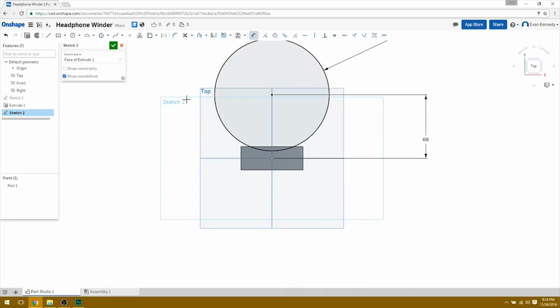So you could either get your circle tool out again and draw another circle and dimension it and position it. Or, just to introduce you to a new tool, we can mirror this. If you click on this mirror tool up here, it says select a mirror line. So you want to choose the line that you're mirroring across. I'm going to choose this, which is actually the top view of your front base reference plane. You click on that and you can see it's selected there now, so it knows. That's turned yellow to say that's what we're mirroring across.